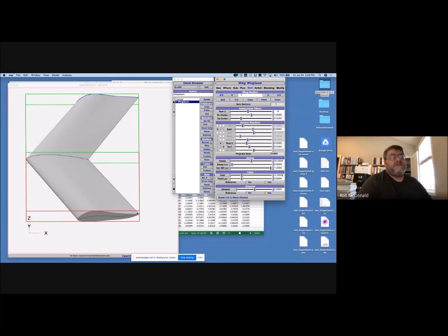And so we made the choice to use symmetrical airfoils. We didn't add any camber at all, because we knew that the moment they would contribute would be 0. So it wouldn't be bad, right? We didn't do anything bad with them. But then we just used twist and sweep to get our stability. That was a choice that we made. Now, you've got somebody like Mark Page, who's really good at airfoils, and you've got XFOIL available to you. So I wouldn't be as afraid as I was back then about the negative moment and the reflex. I think going at it with a combination of reflex, twist, and sweep is a reasonable way to go.